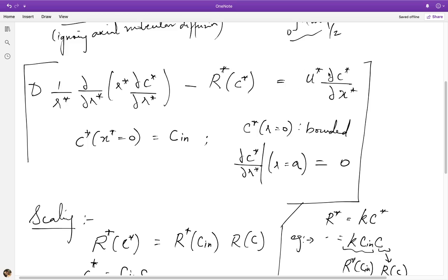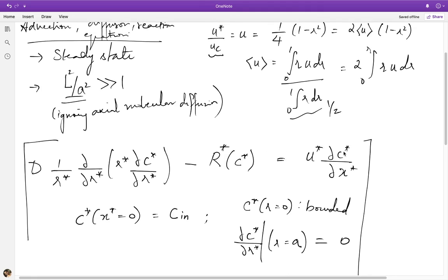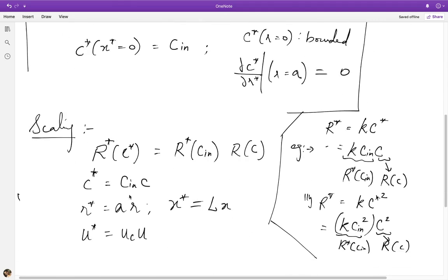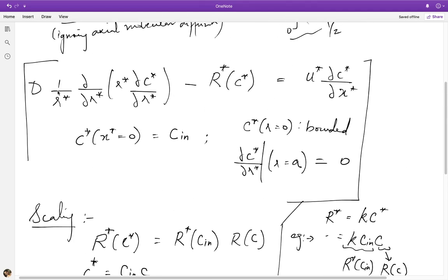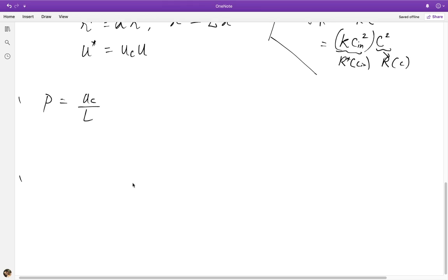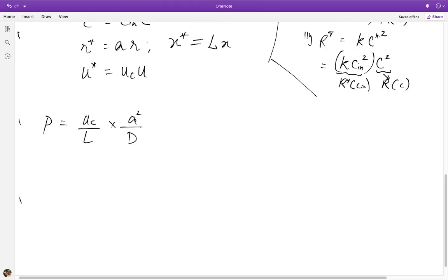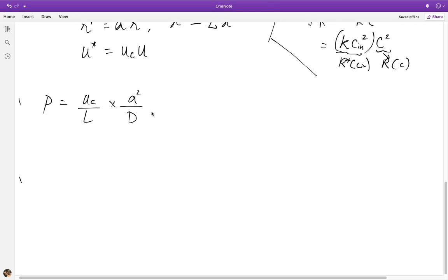Now the non-dimensional group in front of the convection term we have already seen in the unsteady advection diffusion problem of laminar dispersion. Looking at it carefully, I'll get U characteristic over L coming out of here, and then when I multiply throughout by the diffusive group to retain the diffusive term as the leading term, I will get a square over D. The concentration scales of course cancel out from the balance of the advection and diffusion term.